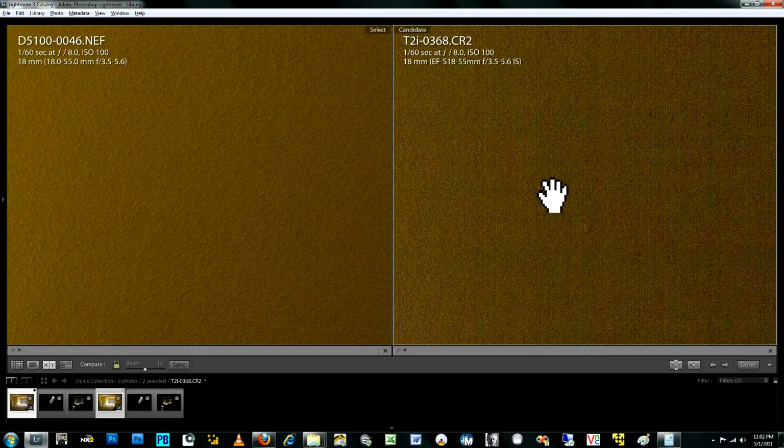Now, this isn't blotchiness from posterization necessarily. This is actually blotchiness as one of the side effects of this crosshatch pattern. This crosshatch pattern is really caused because the individual channels on the Canon body are not perfectly matched. So outside of the difference of noise that you can see in those channels, the difference in actual signals and how they're read off the sensor is different. And that's what creates this repeating crosshatch pattern of these vertical and horizontal lines.